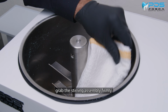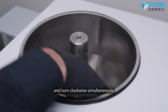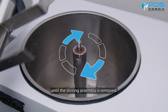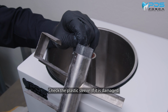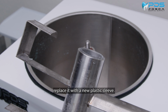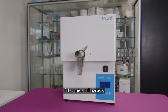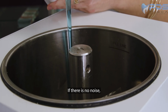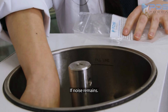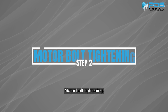Using work gloves or rags, grab the stirring assembly firmly, jerk the stirring assembly upwards, and turn clockwise until the stirring assembly is removed. Check the plastic sleeve. If it is damaged, replace it with a new plastic sleeve. Turn the unit back on for only a couple minutes to check if the noise still persists. If there is no noise, refill the unit and run a cycle as normal. If noise remains, please move on to the next video, motor bolt tightening.